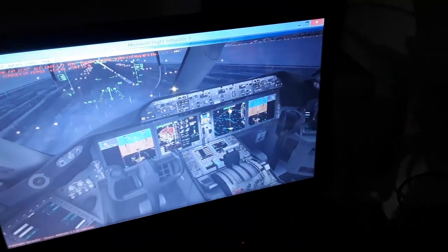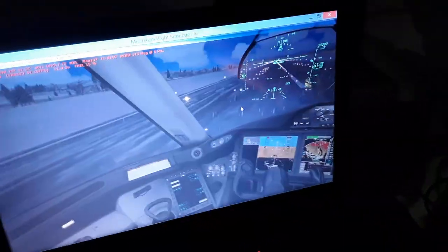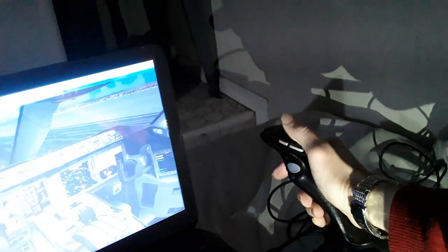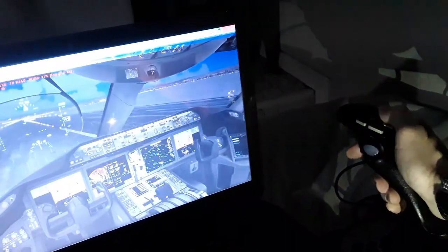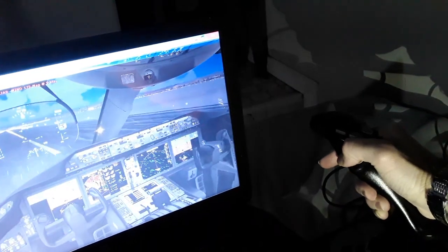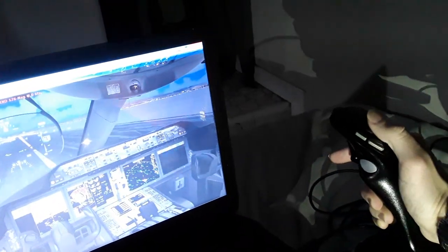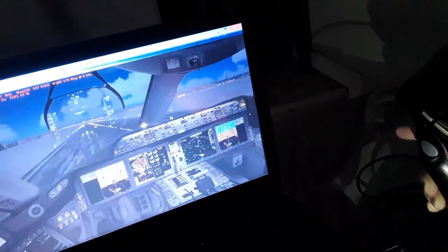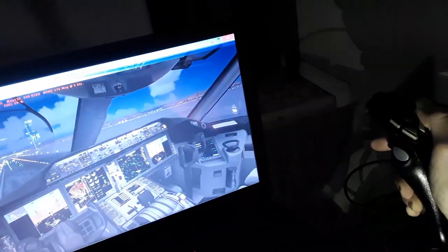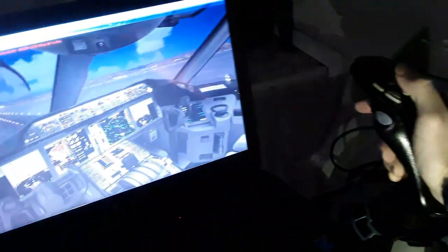So we start now the thrust levers, full takeoff power, everything is set inside the cockpit, as you can see. So we press the side stick down, halfway down, or the yoke, until we reach 80 knots. Also use a little bit of rudder pedal for direction control. So we have 100 knots, 120, 130, V1, we rotate. So we pitch 9 degrees for rotation or less for the Boeing 787, so we won't strike the tail of the aircraft as we climb.